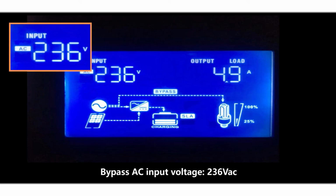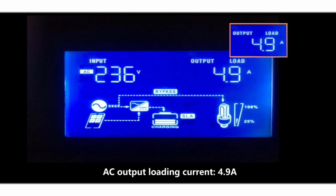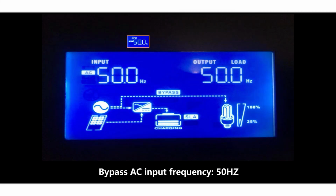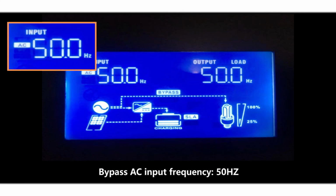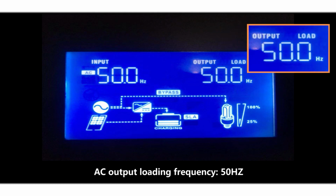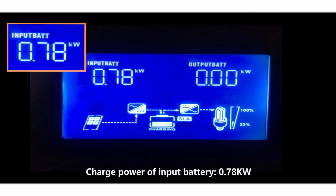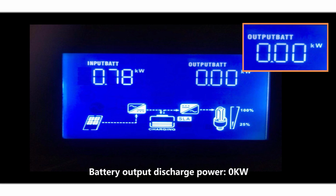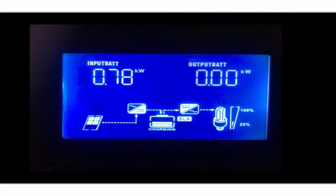Bypass AC input voltage 236 VAC. AC output loading current 4.9 ampere. Bypass AC input frequency 50 Hz. AC output loading frequency 50 Hz. Charge power of input battery 0.78 kilowatts. Battery output discharge power 0 kilowatts.